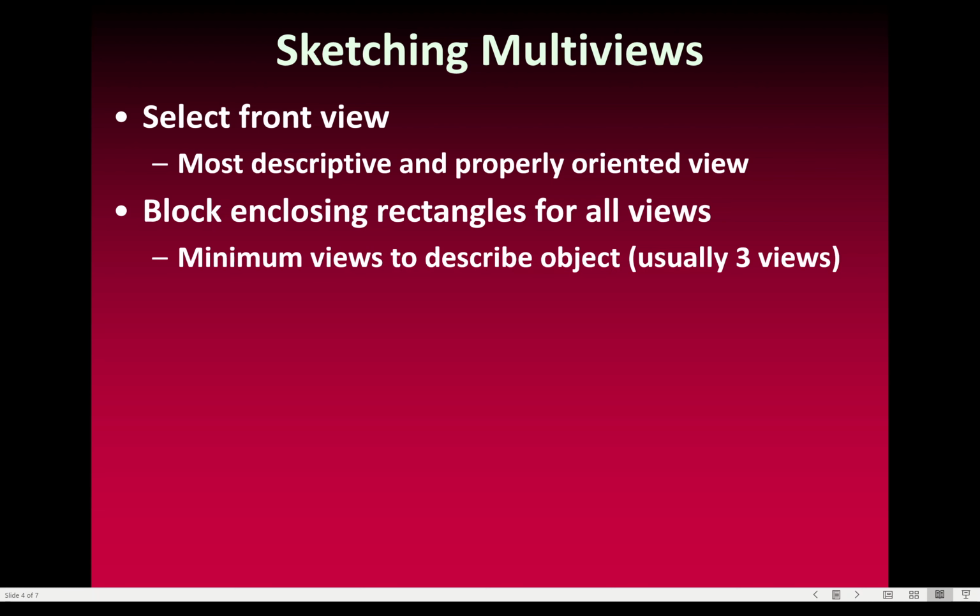The rule becomes, we haven't gotten into dimensioning, we'll get to that later, but if you can dimension every dimension without breaking any of the rules that we're going to talk about, with just two views, then you can get away with two views. But when in doubt, you can always do three views. Again, front, top, side view, perfectly lined up like we got there.